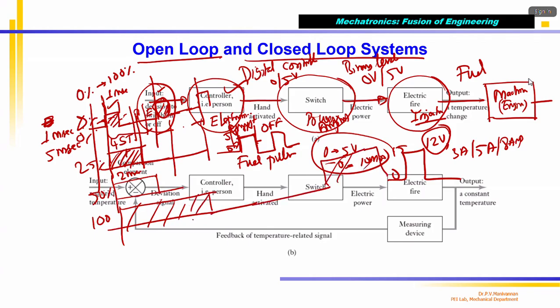So this is how the engine is controlled. We call it pulse width modulation. Correct? Fuel injection will happen during suction stroke. How long the injector is open decides how much fuel quantity is delivered to the engine during suction stroke. So this is how the ECU works. Now, in concept, open loop control, correct?